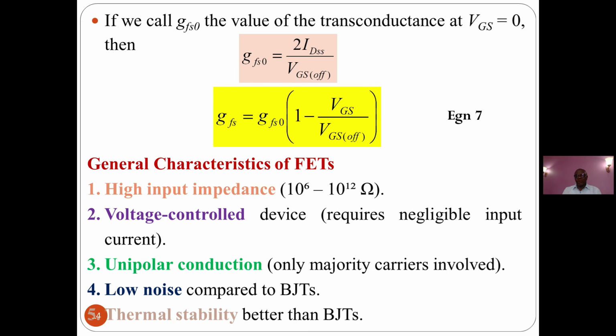So you see that with all these equations, you can determine what is happening, but the important thing for you to note is that the current flow, which is the important thing to us, follows the square law. In other words, a small change in the applied voltage, that is the gate voltage, will give a sharp rise in current flow.